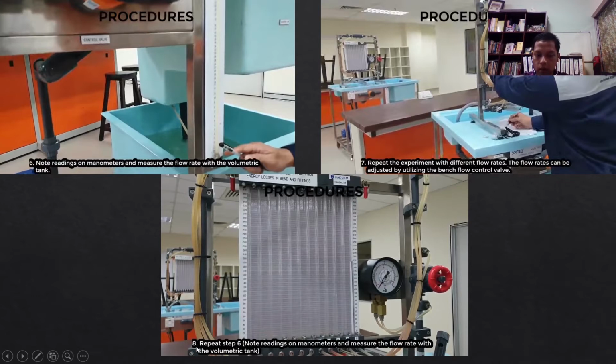Number 8, repeat step 6. Note the reading on the manometer and measure the flow rate with the volumetric tank. So we need to repeat step 6 until step 7.